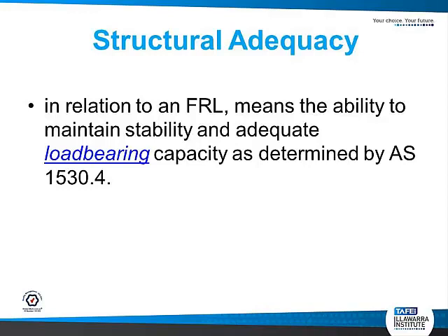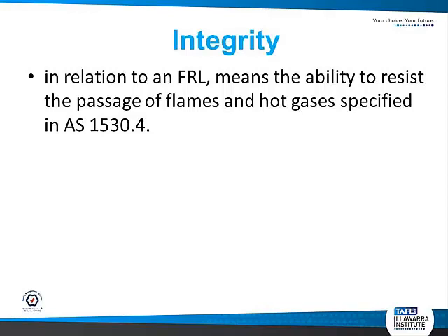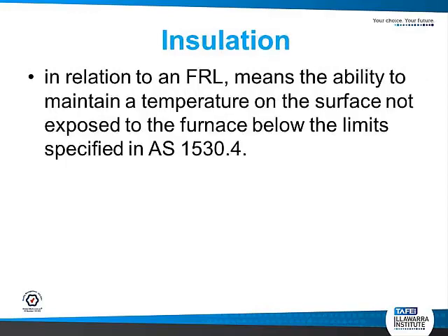In relation to an FRL, structural adequacy means the ability to maintain stability and adequate load-bearing capacity as determined in Australian Standard 1530, and we'll get to what that one refers to in a moment. Integrity in relation to the FRL means the ability to resist the passage of flames and hot gases specified in the Australian Standard as discussed. Alrighty, so check that. You can find that in the definitions section of the NCC.